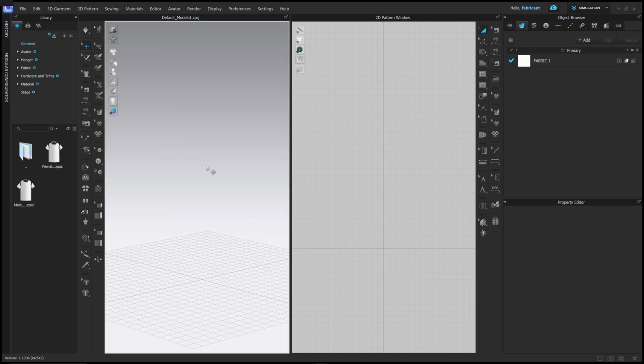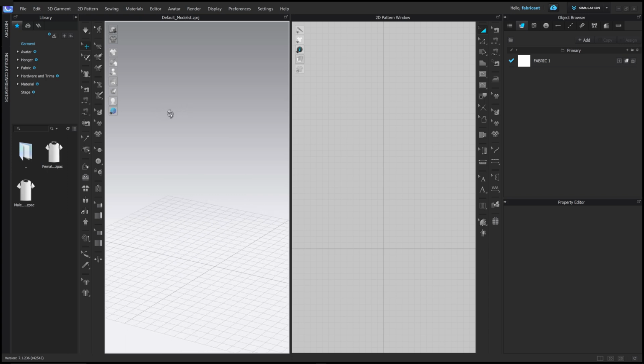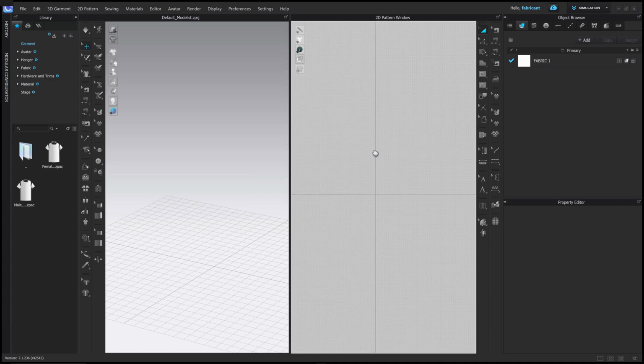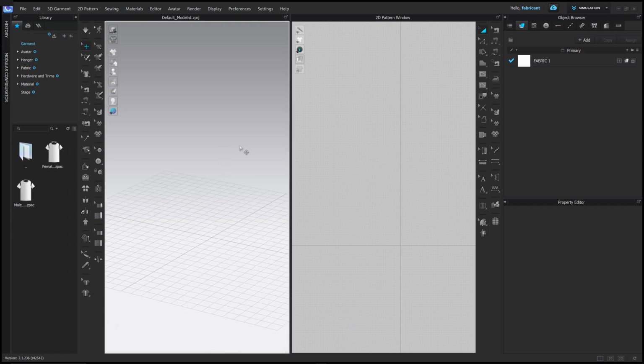So when I'm in the 3D workspace, I can use my right mouse click to rotate the space. You see the ground plane is rotating. I can click the middle mouse button to grab the screen and drag around the viewport. And left click will select whatever is in my workspace. There's nothing there right now. So these are the navigations, and it's the same on this side. Rolling the mouse will zoom in and out, and if I click and drag the middle mouse button, it will grab the screen and allow me to drag the 2D workspace around.